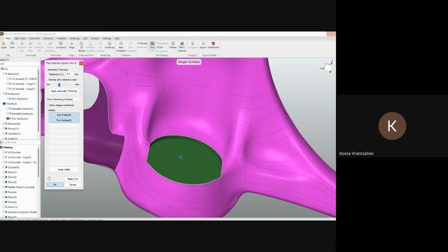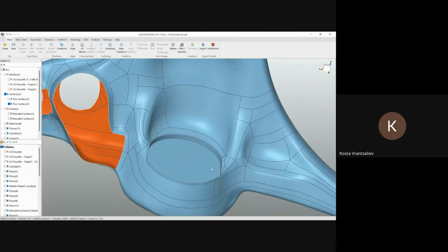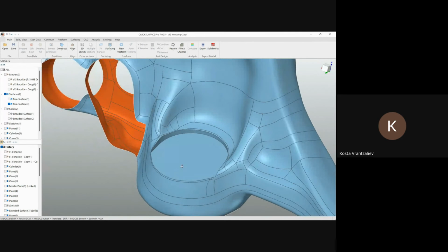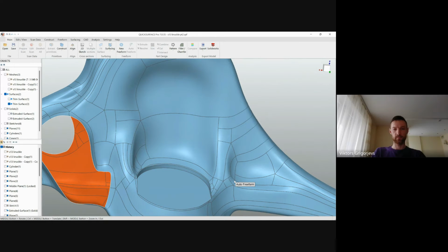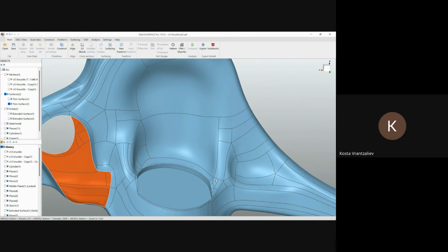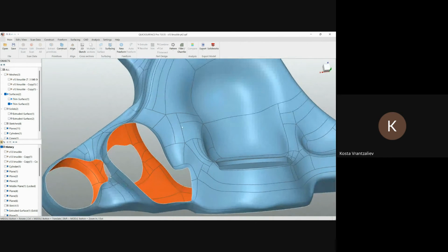It's really important to understand what we do here, because if we didn't make it with this approach, there is no way to make a transition between freeform surfacing and the prismatic shape. So it's always good to extrapolate and try to make this bigger in a nice way so the trimming can work. For the trimming, the main idea is that the surfaces really nicely overlap.